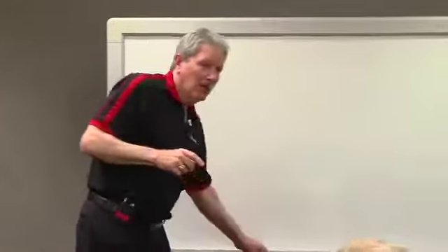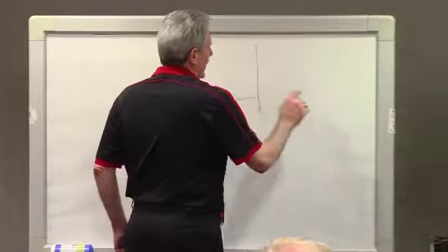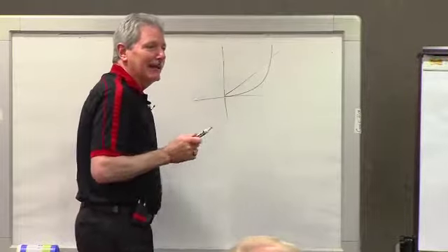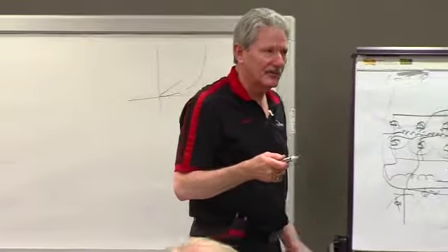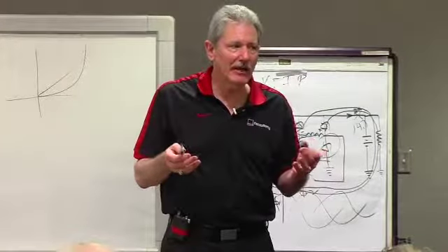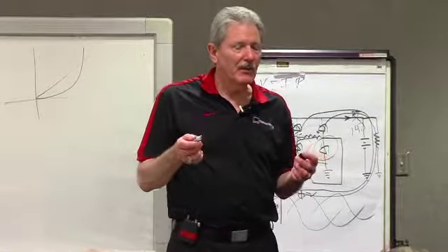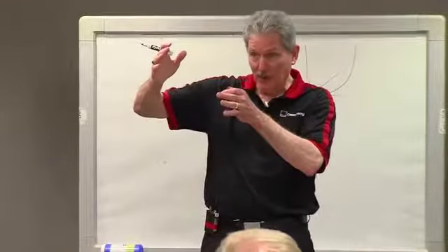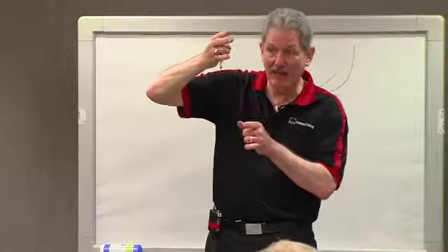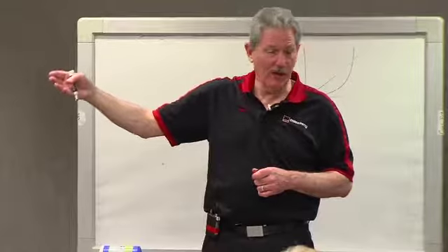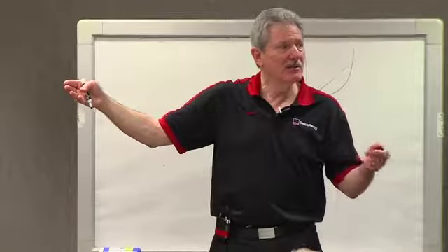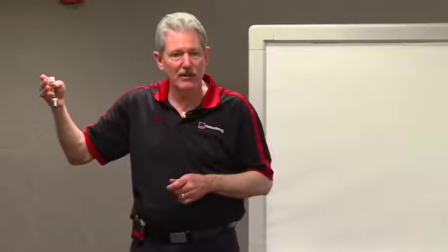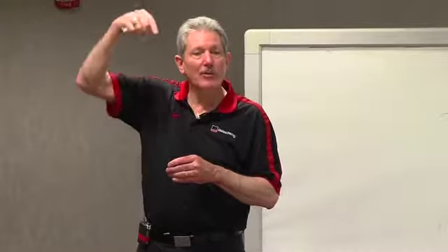The other thing that's good about a MOSFET, this is what a transistor looks like. A MOSFET looks like that. So a MOSFET is resistive in nature. So I don't have this biasing problem that I have with another part. We have a MOSFET rectifier bridge where we're replacing diodes that have that 1 volt with MOSFETs, and the MOSFETs have half of that. So we've cut the losses on our MOSFET rectifier bridge in half by using a different device. So a MOSFET, you apply voltage to the gate, and the equations are there, and it opens the channel.